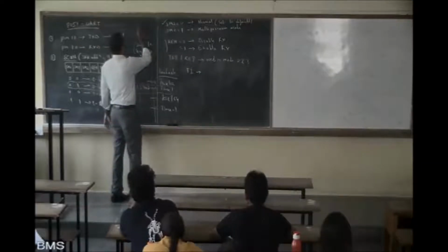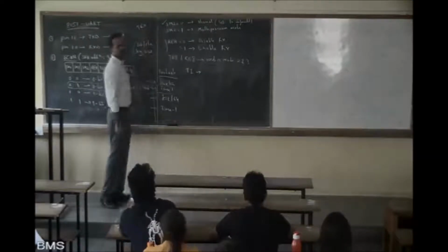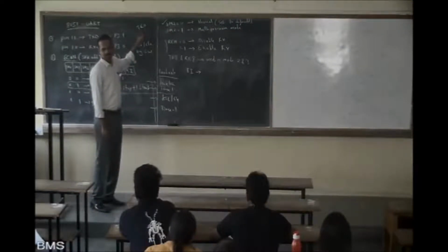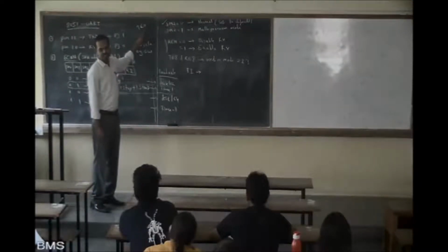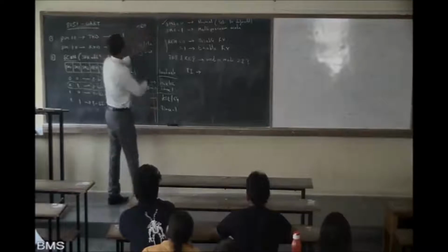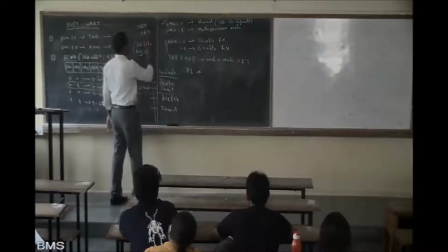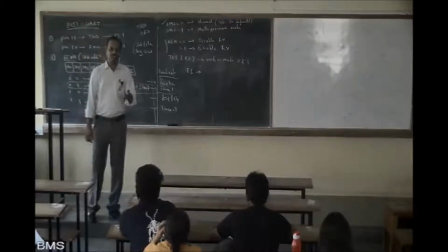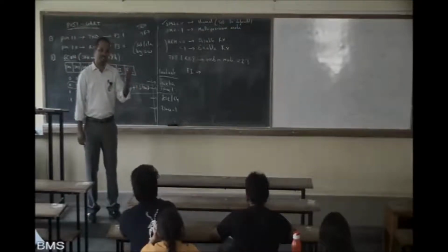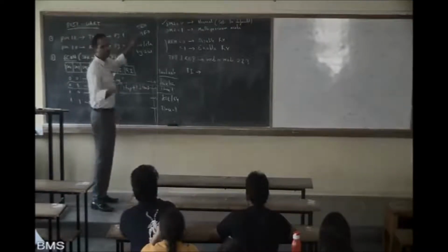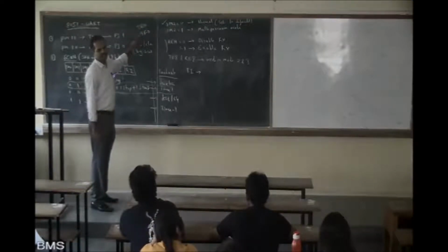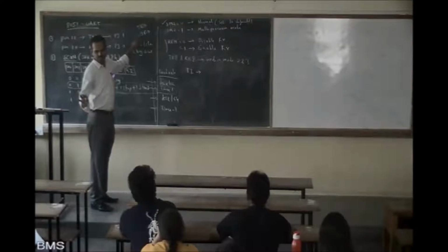For example, the TR0 bit will start or stop the timer. A software instruction has to be given to set this and reset this. Similarly, TF0 is hardware set, software clear. You don't need to set it. It will be set by itself when it overflows, but it needs to be cleared by you. That is why we write the instruction CLR TF0. You know this concept? Clear?